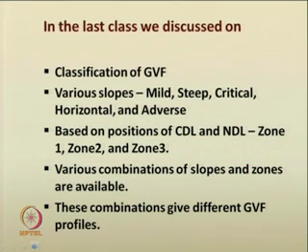Based on the positions of critical depth and normal depth in a flow, you were also introduced to the various zones, that is zone 1, zone 2 and zone 3. If you recall them, say if I just draw it here, say if you have the bed of the channel like this, then if this is your critical depth line, this is your normal depth line, then zone 1, zone 2, zone 3, like this you had classified the various zones where the water surface can exist.